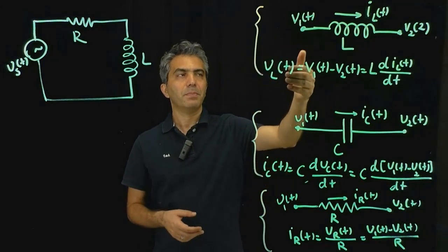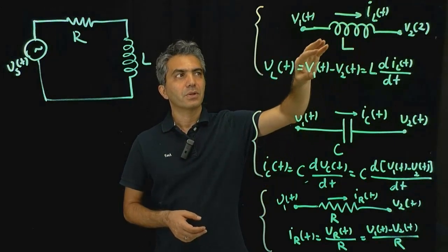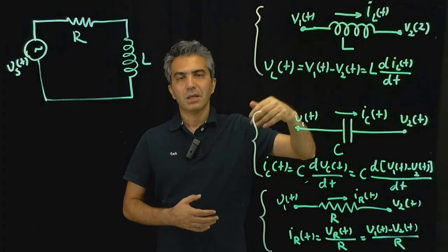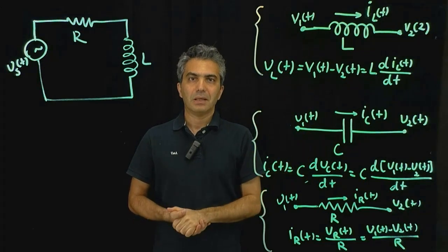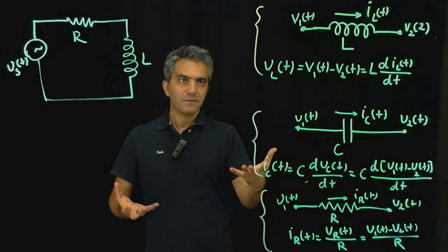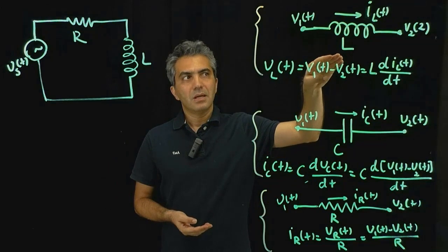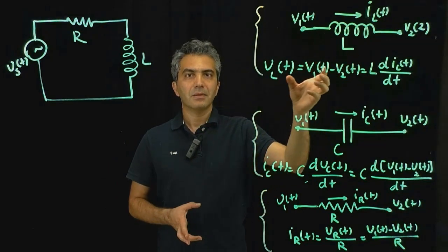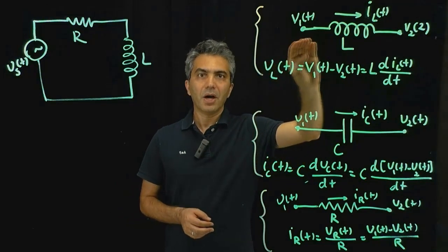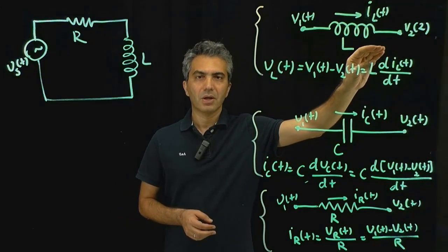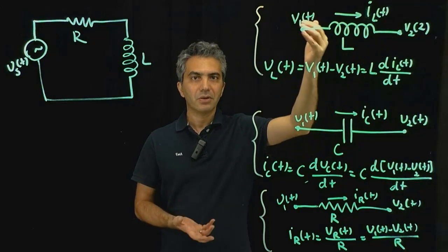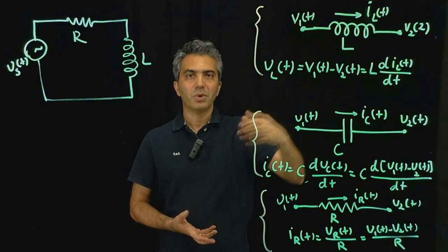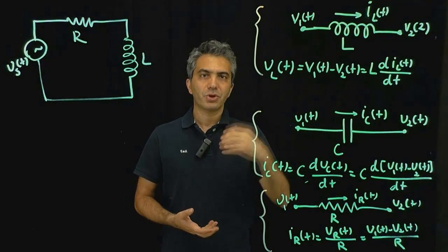As a result, for the same amount of current passing through that conductor, you end up getting a much stronger magnetic field that conserves the energy, and therefore the parameter that represents that coupling between the current passing through the conductor and the magnetic field is going to increase. That is what we call the inductance associated with that piece.